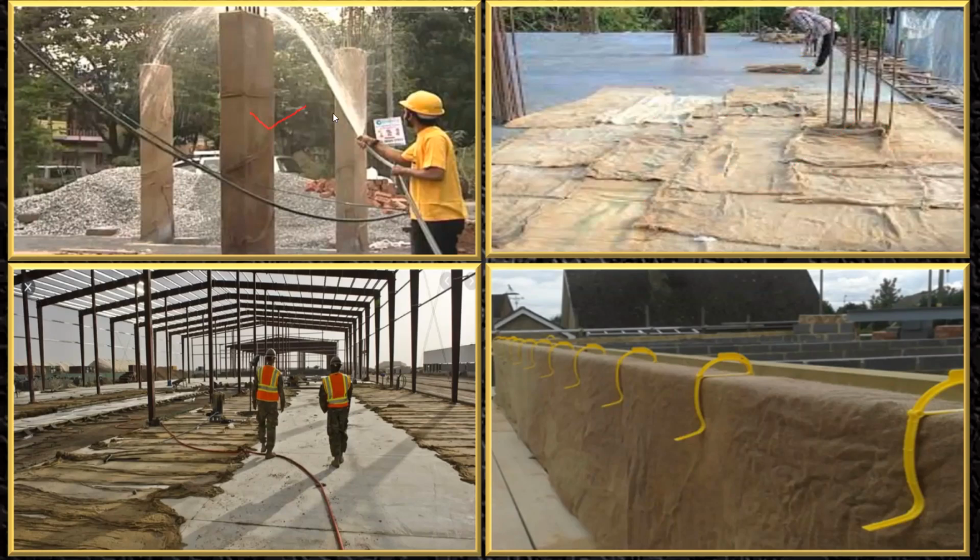Otherwise, what a few people do, instead of wrapping the gunny bag here, is keep a plastic bottle over this. They make a very small hole in the plastic bottle, and this entire bottle will be filled with water. Every now and then the water comes out, and as a result, this entire column will get cured. You have to refill this bottle every 2-3 hours. It's one way of doing it.